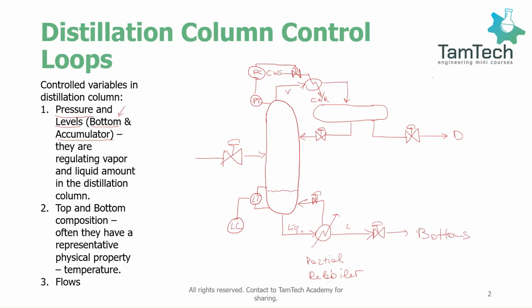So how do we control the bottom level? We are changing the flow rate of the bottoms product. So let's connect it like this. Okay, we connected our liquid level controller to our flow rate of bottoms.